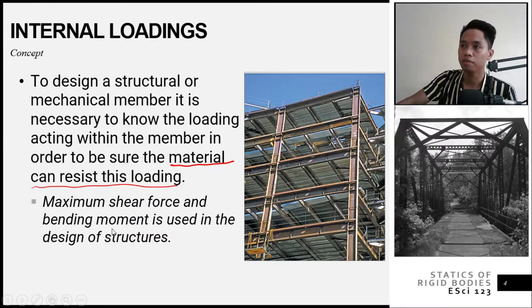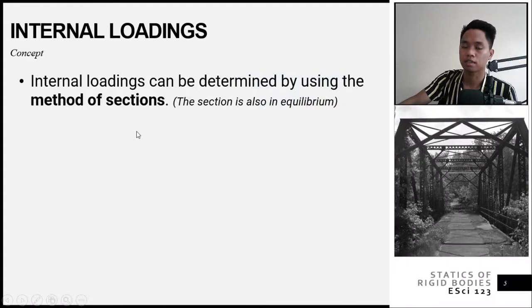Okay? The bending moment is usually the basis for the size of the reinforcing bars to use and the spacing of your bars. Alright? So, the bending moment is your basis for how you design your structure. Now, if you don't have the background of this concept, these internal loadings, you will have a hard time designing your structures. Alright? So, that is its concept.